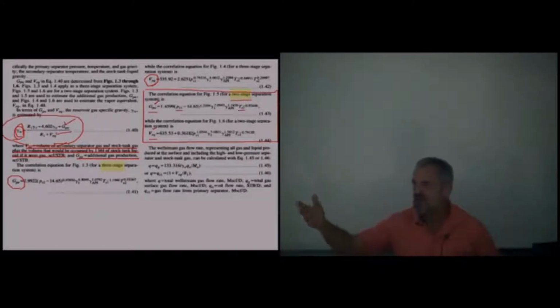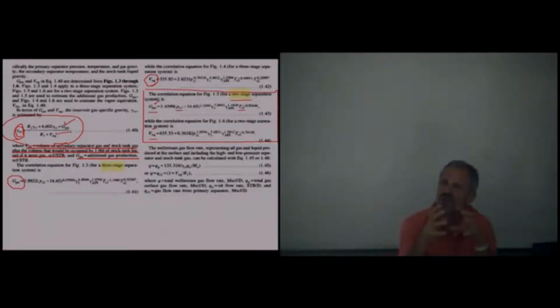We're after liquid. So most of these optimizations, especially now, with gas less than $4 and oil over $100, the situation's never been this drastic or dramatic in the past 40 or 50 years. That oil is this much more worth than gas. So everybody's out there tweaking their separators today, because some separation pressure and temperature will optimize how much of the heavy ends of the gas will cling to the liquid, maximizing the liquid volume.